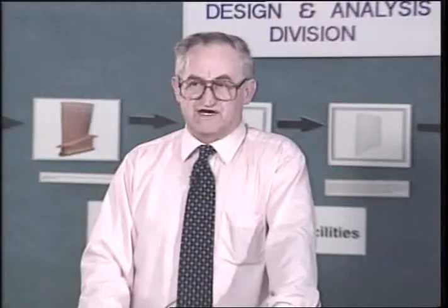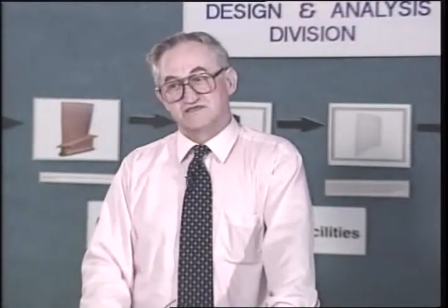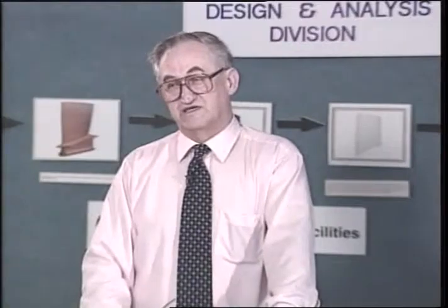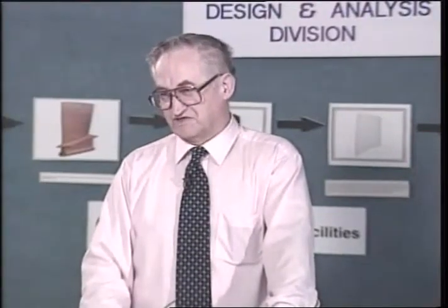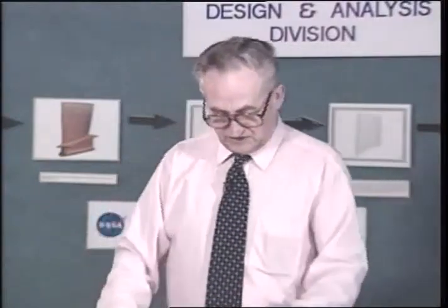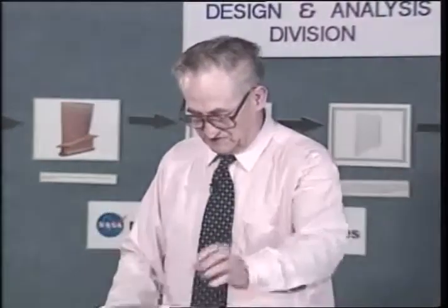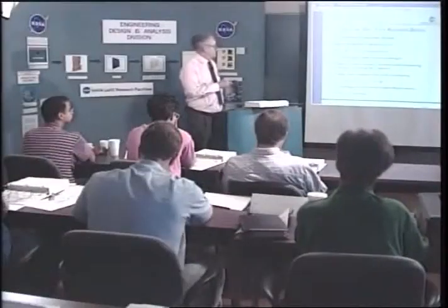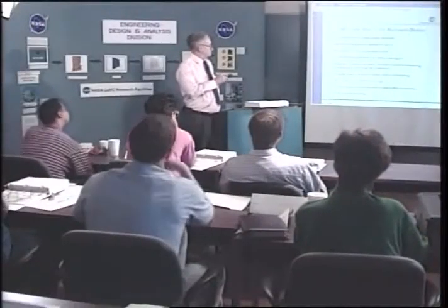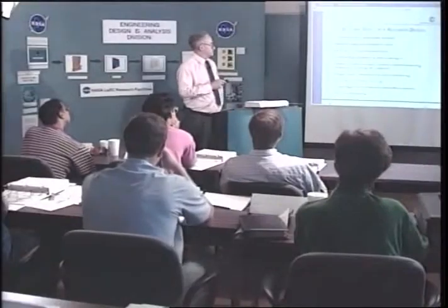So you specify on the drawing in the area of major stress that you want that to be the longitudinal direction in order to get better properties. So specify what you want on the face of the drawing. Now here I mentioned earlier in the course, use a nut that's softer than the bolt.